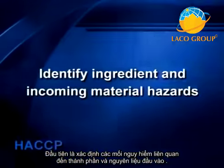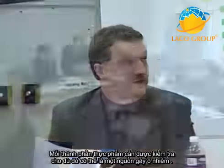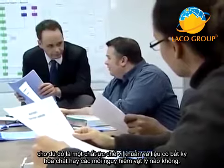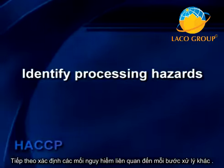First, identify hazards associated with ingredients and incoming material. Each food ingredient should be checked for whether it could be a source of contamination, if it's something that sustains the growth of microorganisms, whether it's a microbial inhibitor, and whether there are any chemical or physical hazards. Next, identify hazards associated with each of the processing steps.